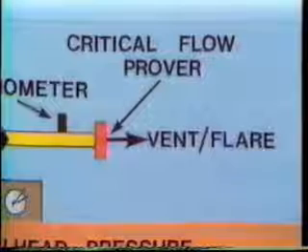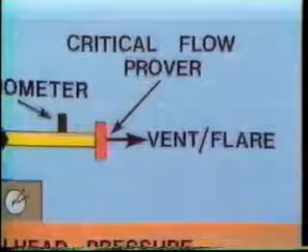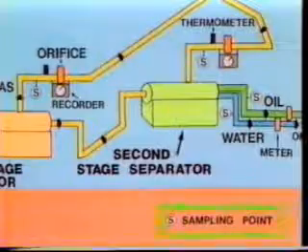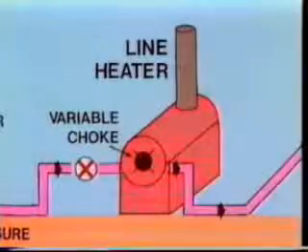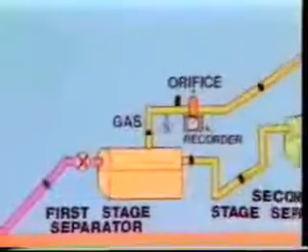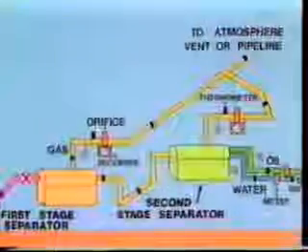If the gas is to be produced into the gathering system, an orifice meter using a permanent or removable meter run is used. The presence of condensate and/or water in the produced fluids requires more complex testing equipment. Now, in addition to the equipment needed for a sweet dry gas, we will need gas and liquid sampling equipment, line heaters, separation facilities, and liquid measuring devices. If 3 phases are present, then 2 stages of separation are required.